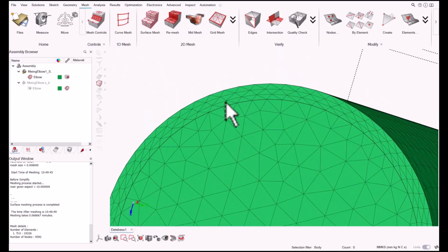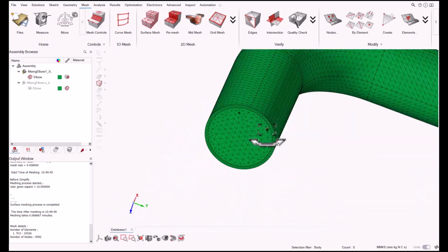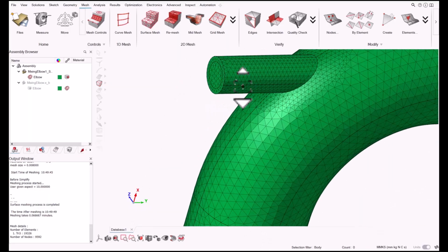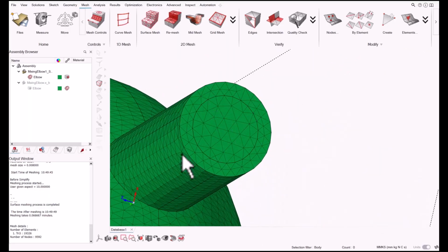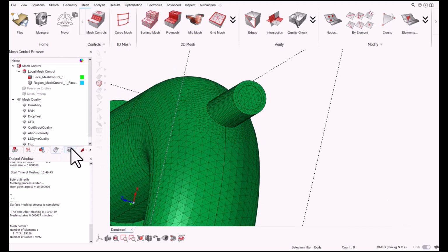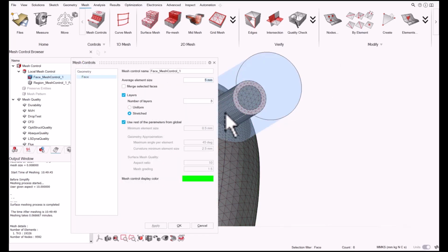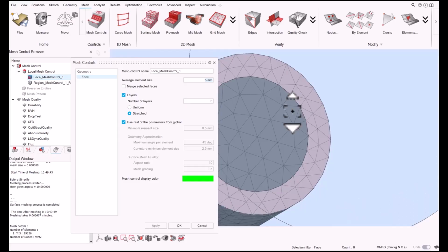Okay, so we have three surface mesh layers for the solids, but we don't have three surface mesh layers on the fluid. This happened; for some reason the surface layers aren't respected.